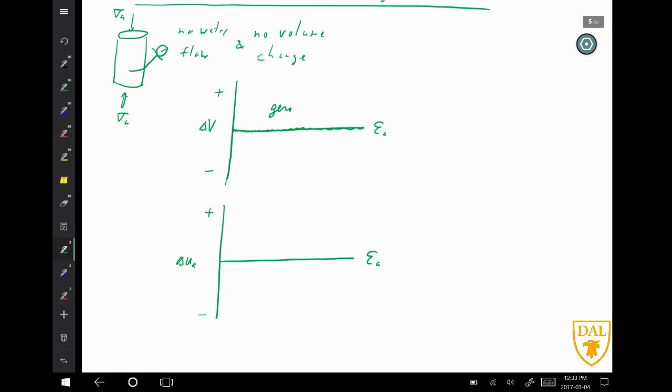And a soft soil is often what we call a normally consolidated soil. And stiff is characterized by an over-consolidated conditions. Okay, so the normally consolidated soil, or soft, has a tendency to have an increase in pore pressure with loading.